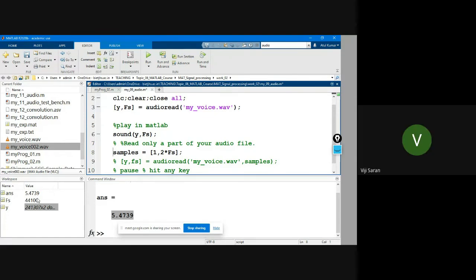For audio, we have 20 kilohertz, right? That into 2, maximum they have considered 44K. Yes, we can do 20 kilohertz also. The sampling frequency should be greater than the signal frequency. Two times the signal frequency, that is Nyquist. Maximum signal frequency into 2 should be less than the sampling frequency. Otherwise, you cannot reconstruct or retrieve the signal back. That is the Nyquist criteria that we always have to follow, otherwise it will not be right.